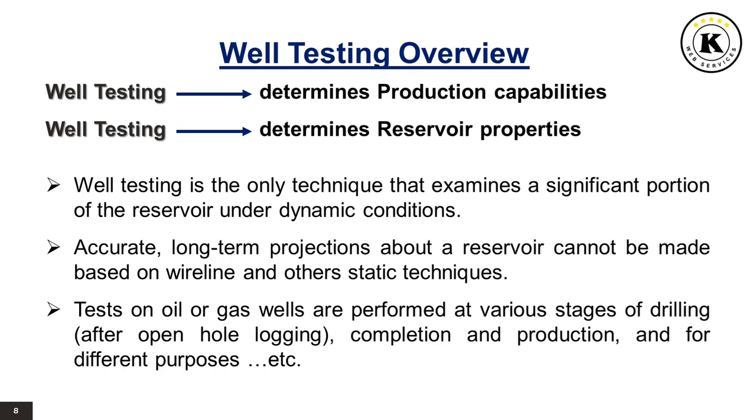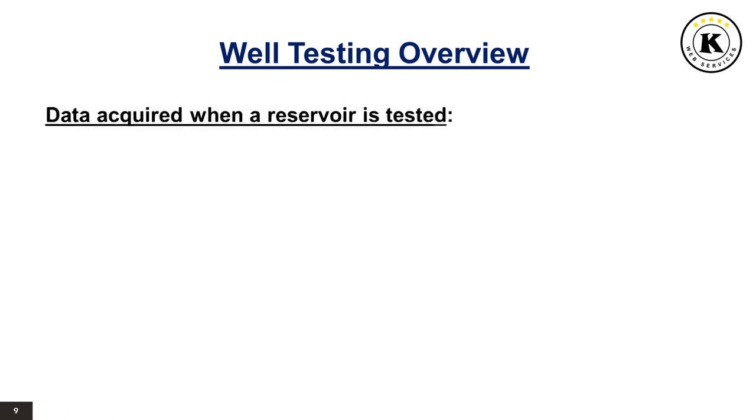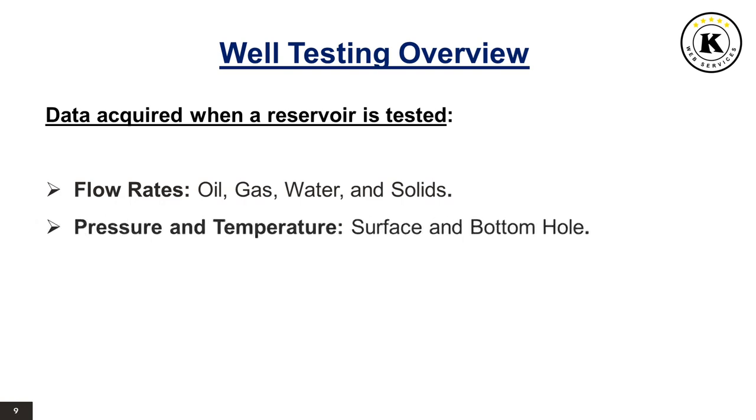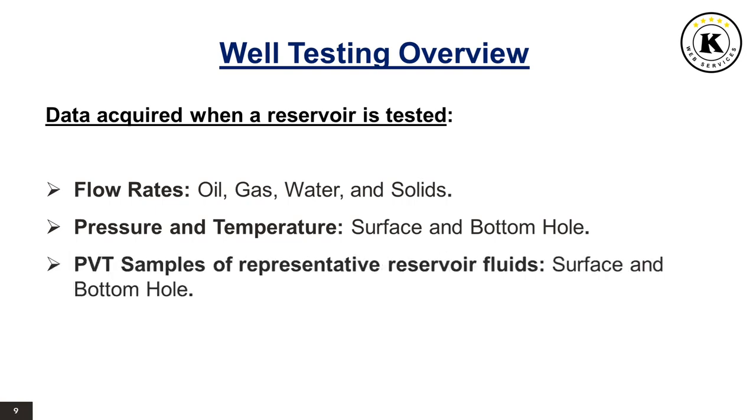for different purposes. The data acquired when a reservoir is tested includes the flow rates of oil, gas, water, and solids produced, the pressure and temperature recorded at surface and at bottom hole, the PVT samples of representative reservoir fluids collected at surface and at bottom hole.